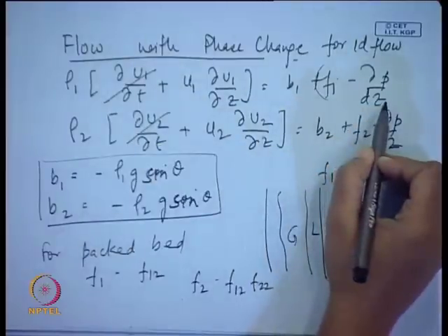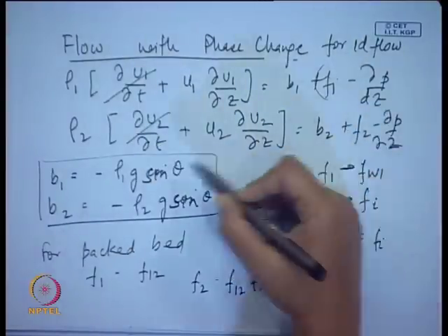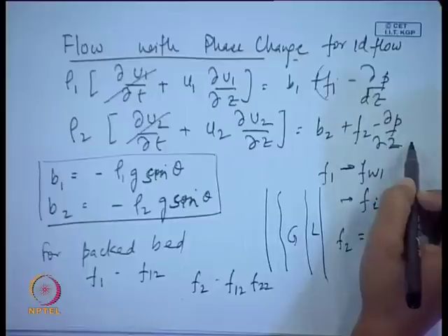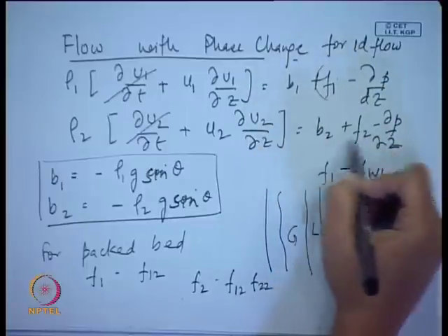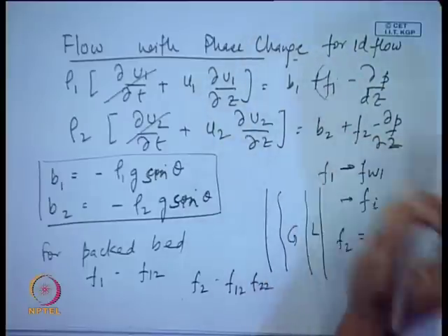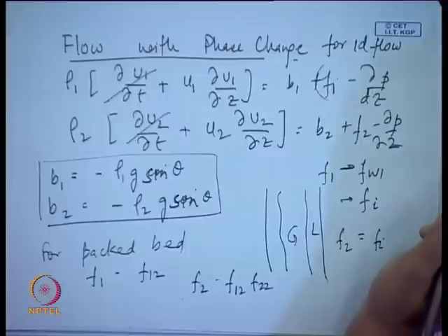Now, as we go more and more complex, the derivation from first principles becomes slightly more elaborate. It is not that it is impossible to do it, but it becomes slightly more elaborate. Okay. So, therefore, what we do, we just take up the basic momentum balance equation for phase 1, basic momentum balance equation for phase 2. If you can substitute all the terms accurately, we can simply add them up and we can get the momentum balance equation for the mixture. Clear to all of you?